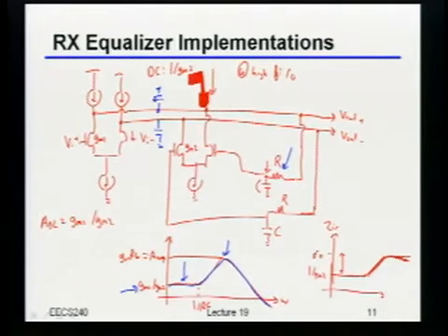Two stages of power. So, is it noise? Does that amplifier right there give me any extra bandwidth? No, right? What is the only purpose that amplifier is serving? Impedance. Yeah, all it's really doing is lowering the impedance at DC, right? So in other words, I'm spending power to basically throw away gain.